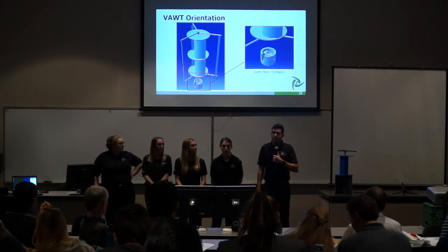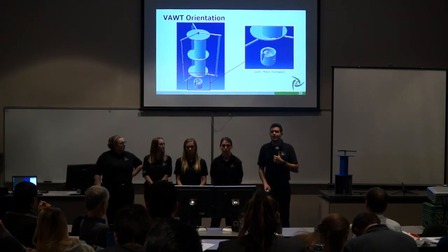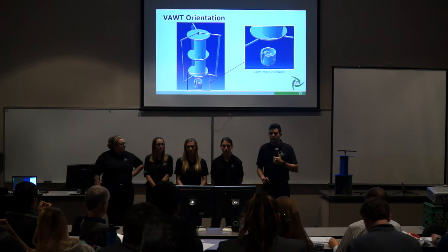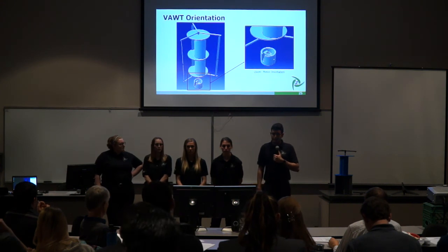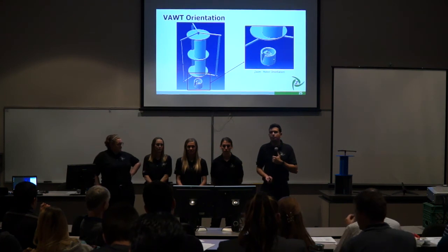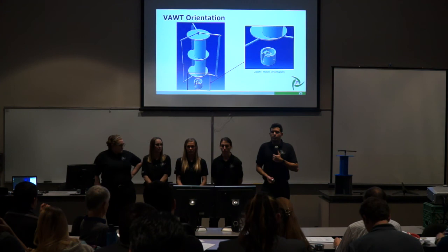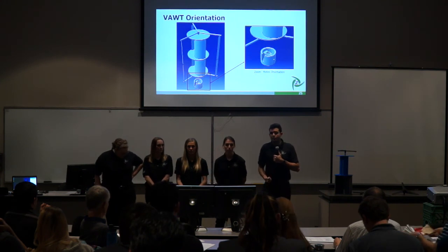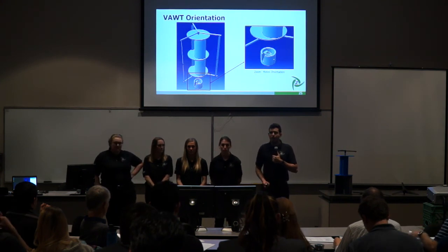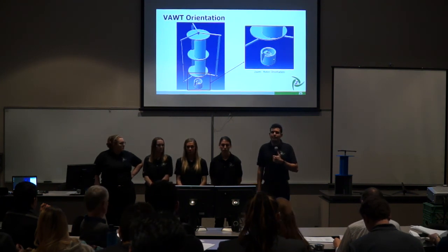We actually did analyze a same class motor in the NEMA 17 HS class, but a lower holding torque and lower rated amperage motor version. Even at the 1,400 RPM range, as with this one, we got 12 watts out of it. That one only got around 8 watts out of it. So we haven't analyzed another motor, and that's why we went with this one, because it is a little bit more powerful. So we can specify this is the one that it is designed for, but if you choose to use another motor, you might not get the same outputs.